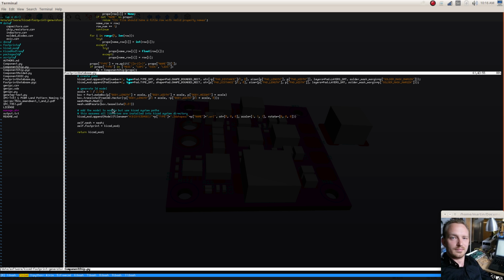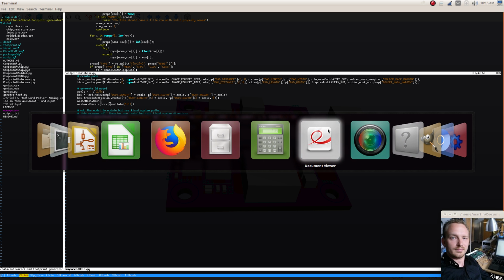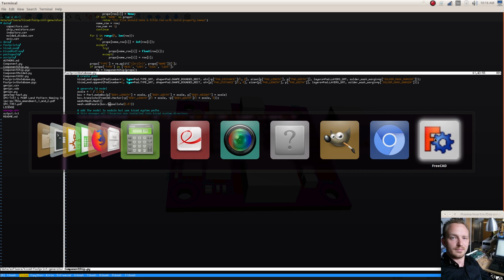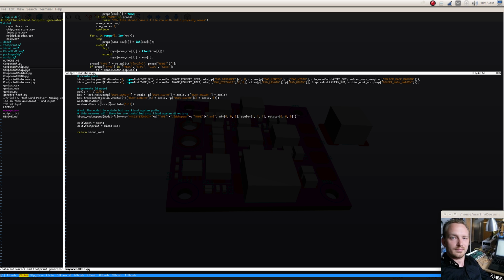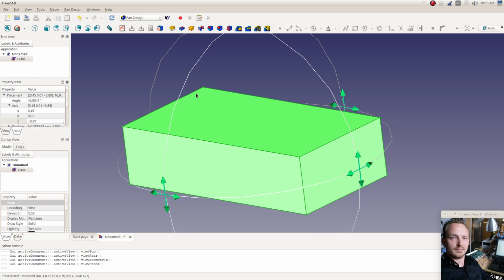So it's not really trivial, and like exporting the different export functions in FreeCAD, they're actually located in different modules. So it's like, well, okay, it's really not organized the way you would expect it to be organized. But the good part is that in FreeCAD, when you actually open FreeCAD, you can see all of the commands that it's executing, all of the Python commands here.